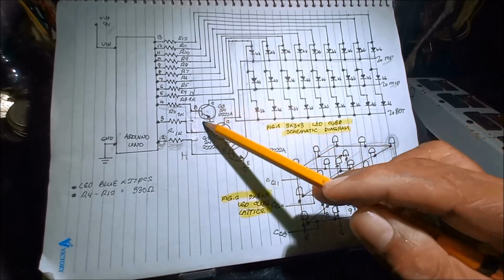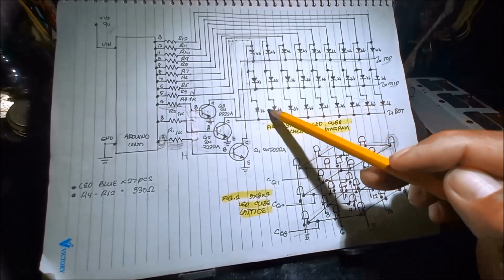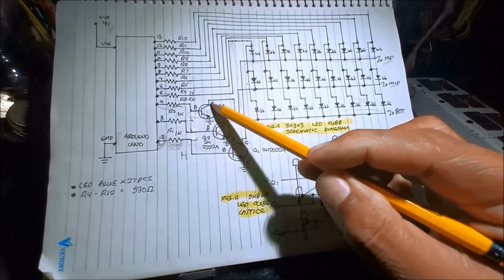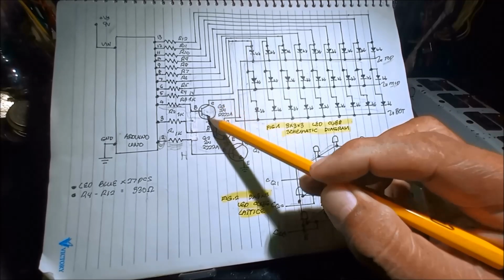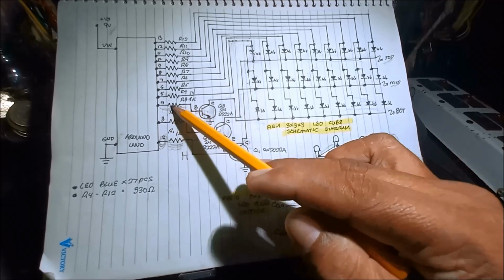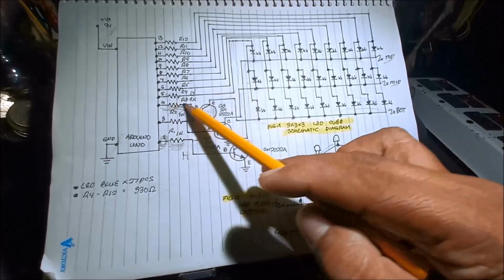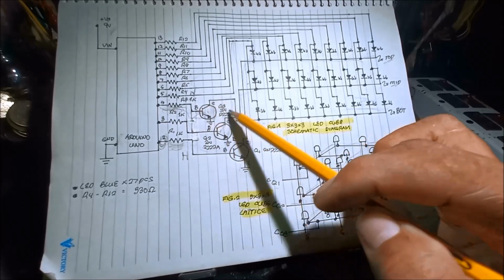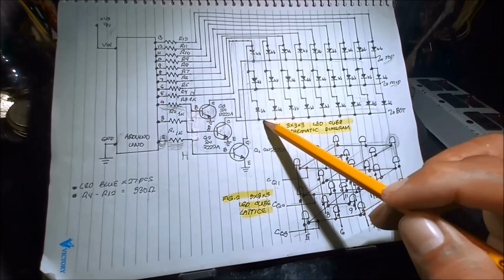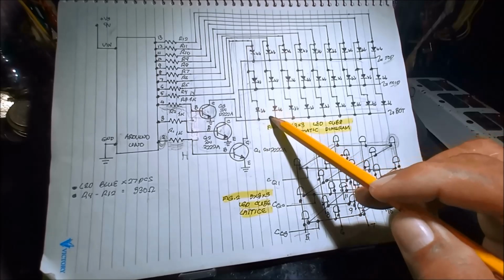So it can carry all these LEDs to the collector of this Q3, and then turning on this transistor, because we are setting this pin number 4 high. So we have now the output, forward biasing, and then all these transistors are active.